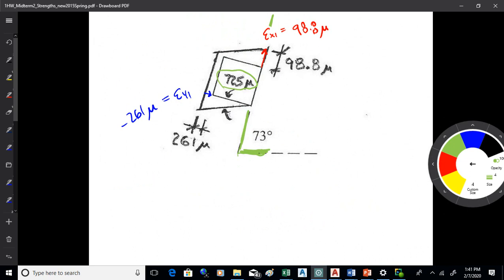So we're doing all right with that? Okay. So you do have to kind of learn that strain convention for how to make the sketches. It's just a convention. So that's the first one there. The same thing as biaxial stress. I do think the stress stuff is more important because stresses will actually cause something to fail or something you pay an awful lot of attention to. Strains are a little more about deformation, which may not be important depending on what you're doing. Okay.